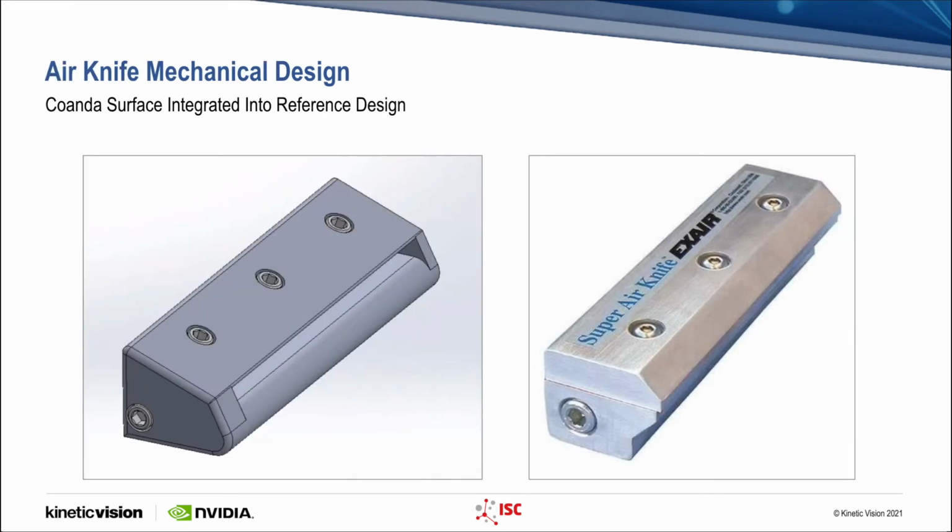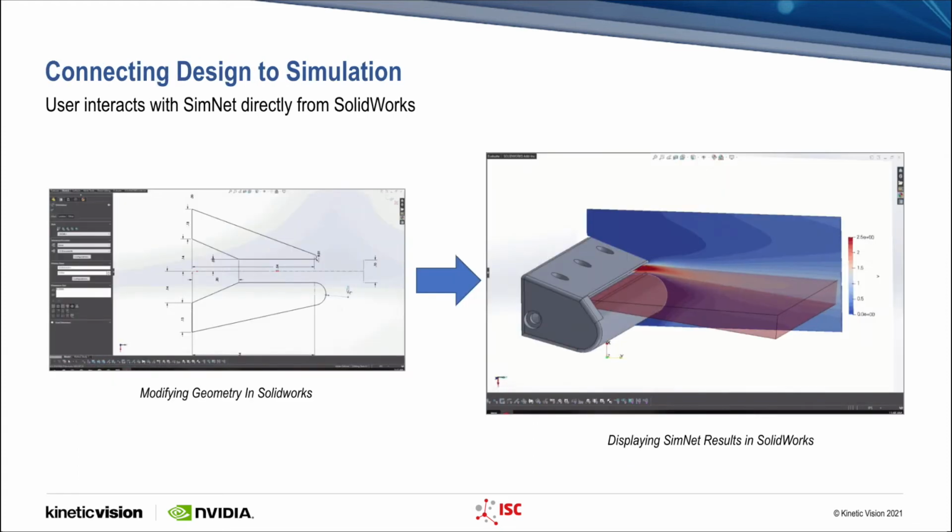So this is the design for the air knife that we chose. On the right-hand side, you can see a normal commercially available air knife, and then on the left, we designed an air knife that takes advantage of this Coanda effect on the bottom surface. And as you interact with the CAD model, really what you do is just like using SolidWorks on an everyday basis. You're going to select your sketch, change the radius value of that lower trailing edge, and then that's going to adjust the solid model. And on the right-hand side, you can see we're showing the results at each different radius as we cycle through that design space.